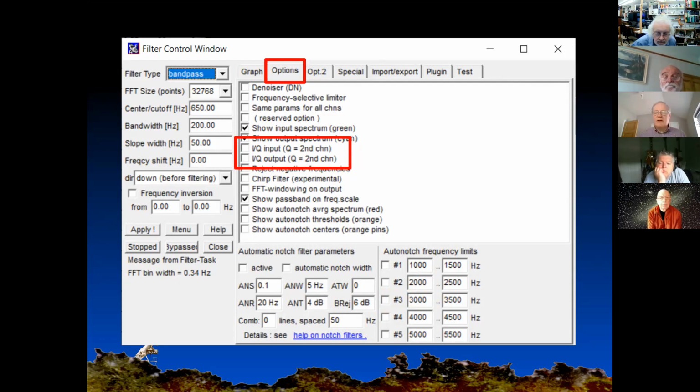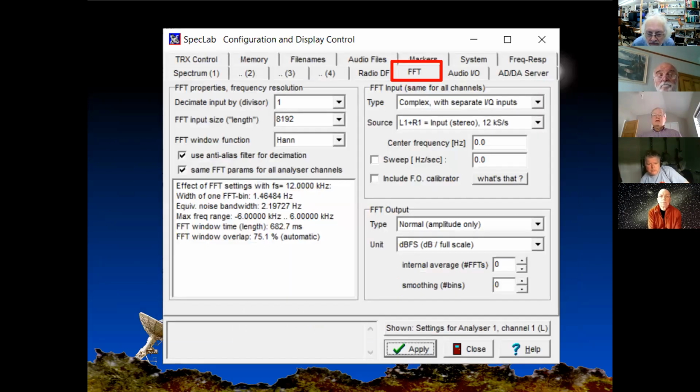But unfortunately, it only removes static frequencies. It doesn't track a frequency and move it as it drops through the frequency range that you're looking at. But anyway, onward. Okay, there isn't a block on that schematic saying FFT because it underlies everything, but I ought to say something about it.